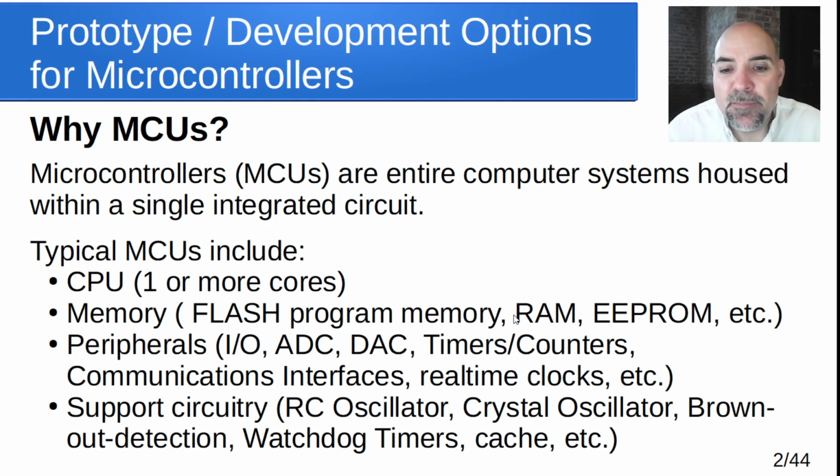All right, there's also a lot of times, inside that one single chip, some of the support circuitry you need. Some of them don't need a crystal, because there's an RC oscillator. Or if they do need a crystal, the crystal oscillator circuit that makes the crystal ring and makes the clock tick, tick, tick is built in.